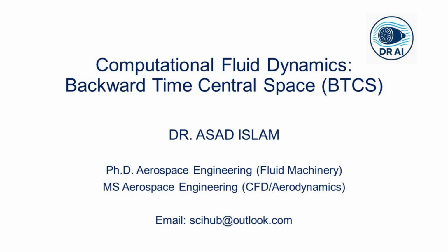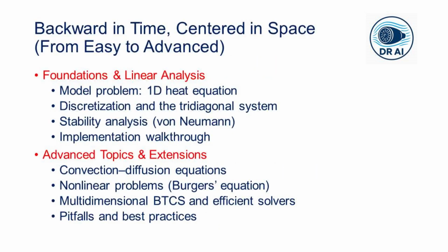Welcome everyone. Today we are going to explore one of the most important finite difference schemes in computational fluid dynamics, the BTCS scheme. BTCS stands for backward in time centered in space. This is an implicit scheme and it's the foundation for many solvers that handle diffusion problems, with extensions. It even appears in algorithms for the Navier-Stokes equations.